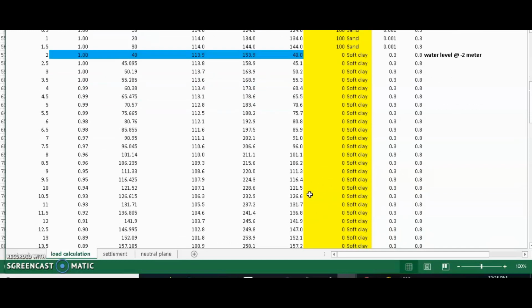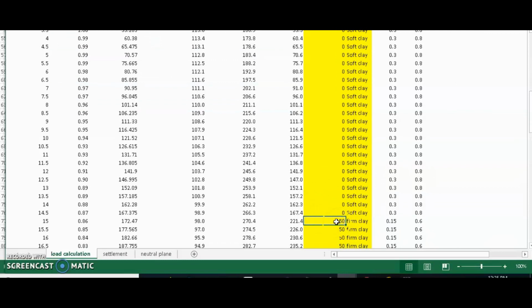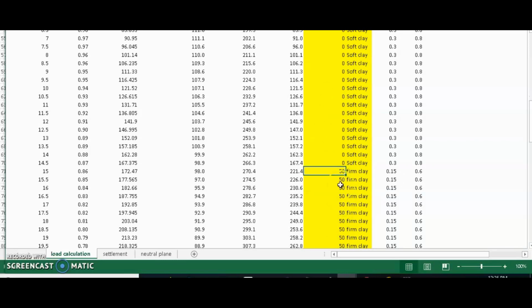So in the case of over-consolidated clay or some other specific case, you plug in a value other than 0. Zero is actually for most cases, normally consolidated clay, and for previously consolidated conditions you should specify the degree of consolidation here, which is your starting point of settlement.